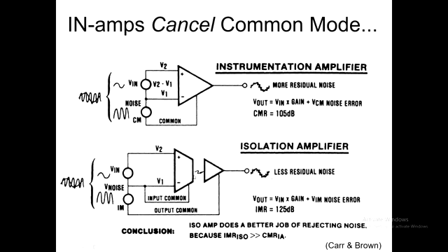So the isolation gap here has a galvanic resistance associated with it, and it is that which isolates out a common mode signal between input and output. So the mechanism, as you remember, with an instrumentation amplifier is that common mode signal gets neutralised by subtraction, the differential aspect.